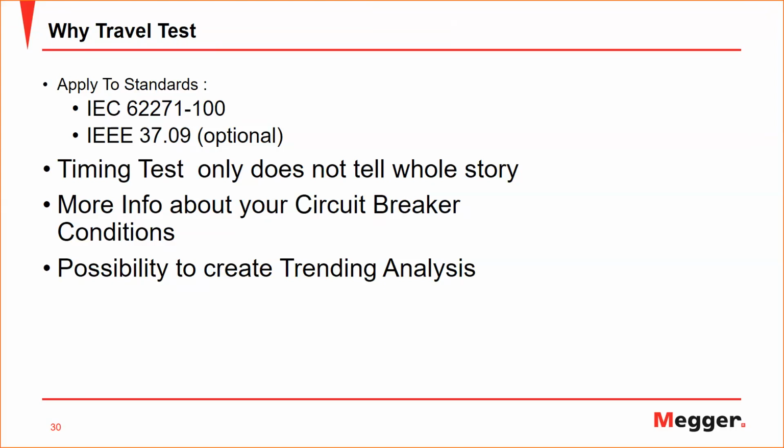Travel test is applied by standard. It is a standard test that is required not only at the manufacturing site, but also during service, in substations and on site as well. And the reason why the standard requires that is because when you do timing test only, it doesn't tell the whole story.